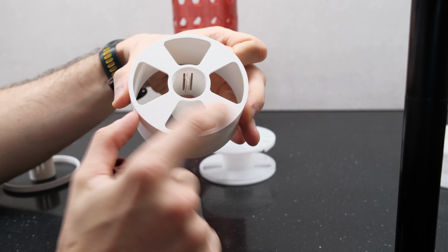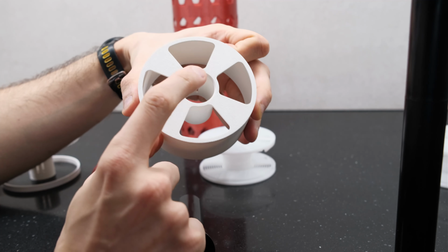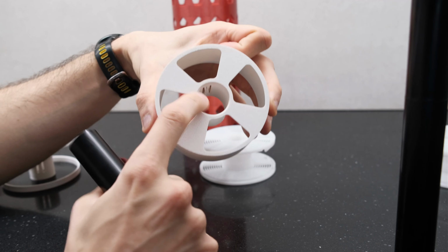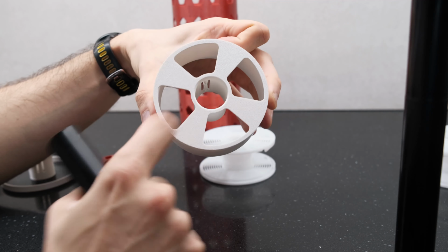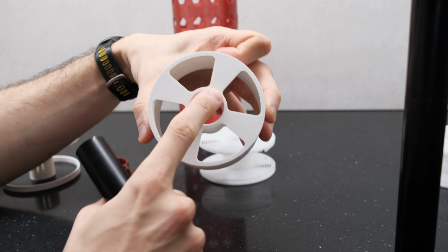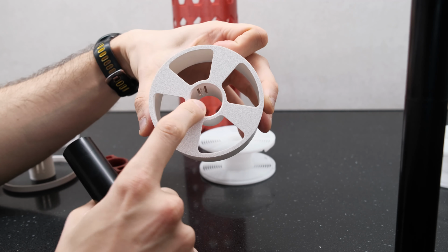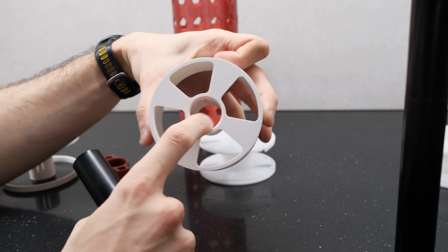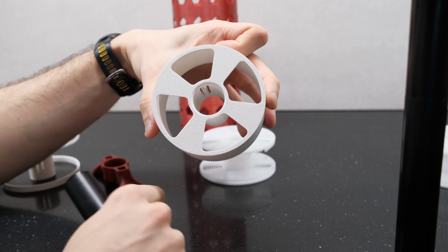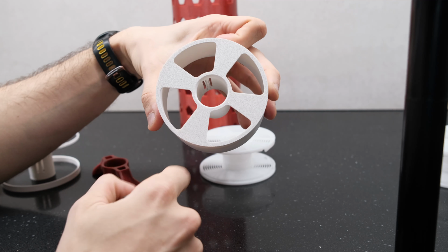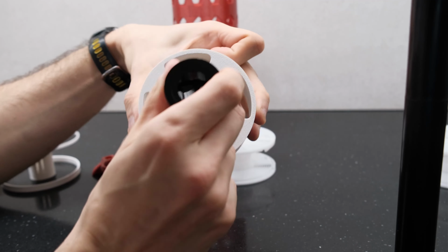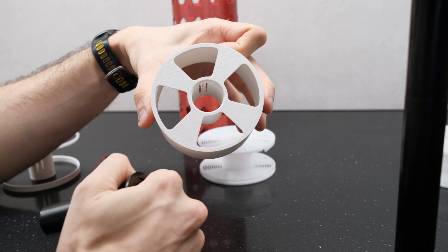And as you can see here, you see the pattern from the table. So it means the angle of this bevel here should be not more than 60 degrees. If I make it 45, there can be a defect here on some printers, not modern ones, or if you print too fast, or you have problems with the material. So think about that. If you make a longer path here, it works exactly the same, but you remove the problems with the printing.